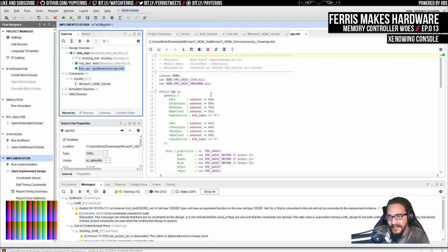If it's in the low 4 values, you make it high, otherwise you make it low. So you just take the high bit, for example, which would give you the other way, but it doesn't really matter. That's a really easy thing to do. And that's actually what I did in the existing design. Right now it runs at 100 megahertz, and then every 4 clocks I change the output values, and then I take the high bit for the pixel clock output.